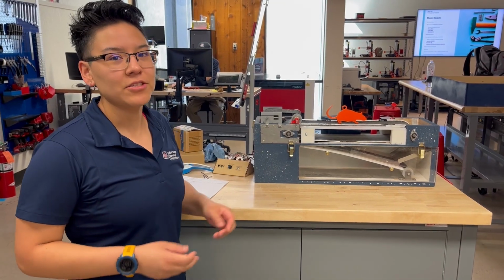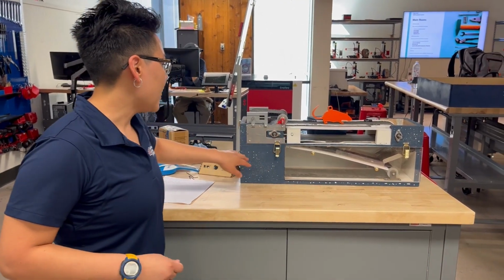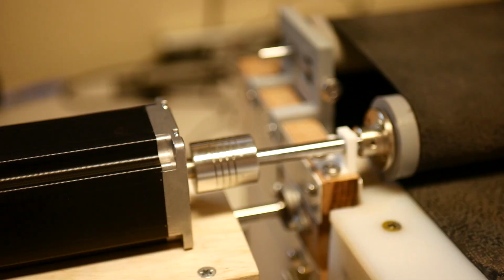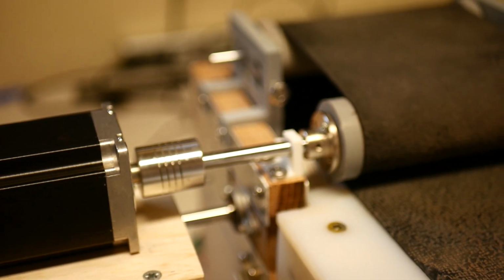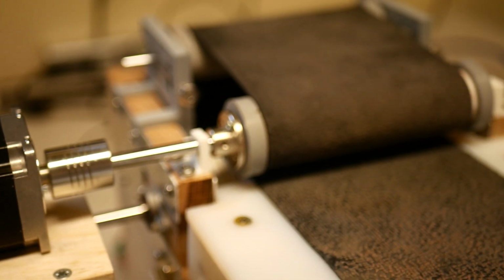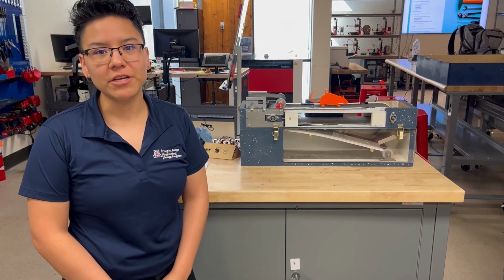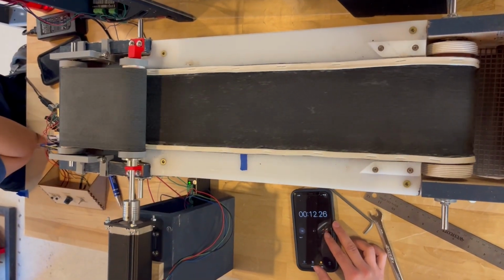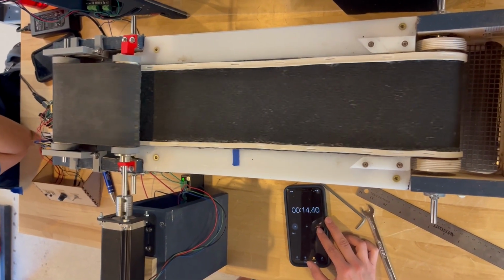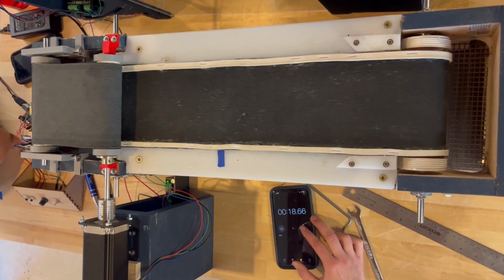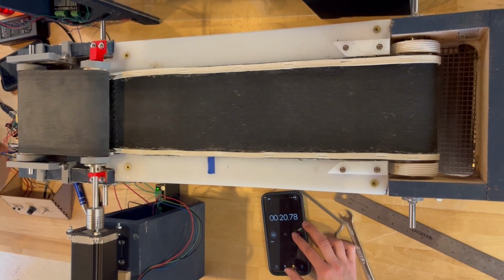The treadmill subsystem was designed to incorporate the FRT and harness subsystems while facilitating ambulation. Some challenges that we encountered were roller traction from the back, belt alignment slippage, as well as conveyor belt material. The verification procedure of the treadmill ensures that it operates at the same speed as the rodent's ambulation. Additionally, it will operate at the same speed as the SRT.